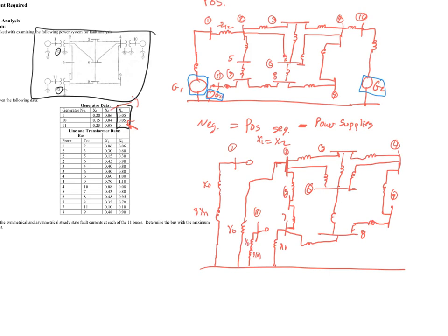The final connection we have is bus 4 to bus 10, and that's a YY, so that's just a straight pass-through of the impedance. This is bus 10, and then we drop through our generator impedance, which we have an x0, and then we also include the xn, which is a non-zero value, so we have 3 times xn. So at this point, we have everything we need to go ahead and build our Y buses.